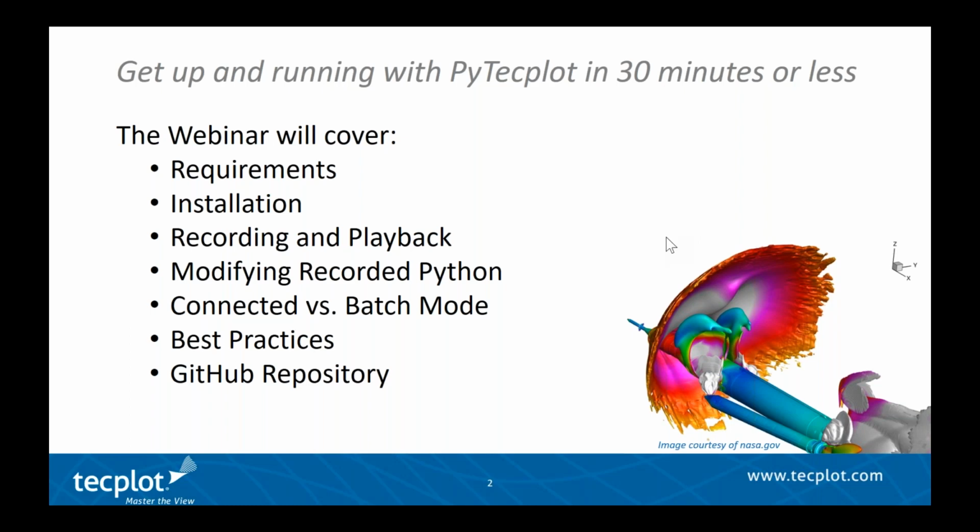We're going to show you the difference between running a Python script in what we call connected mode. So that's a way that you can actually drive the Tecplot 360 user interface with Python. And we're going to also show you running a Python script in batch mode. So that would be useful for image generation, data extraction, data generation, also running headless on, say, a cluster or HPC. We'll show you some best practices and then we'll apply those practices back to the recorded Python script and modifying that script a bit further.